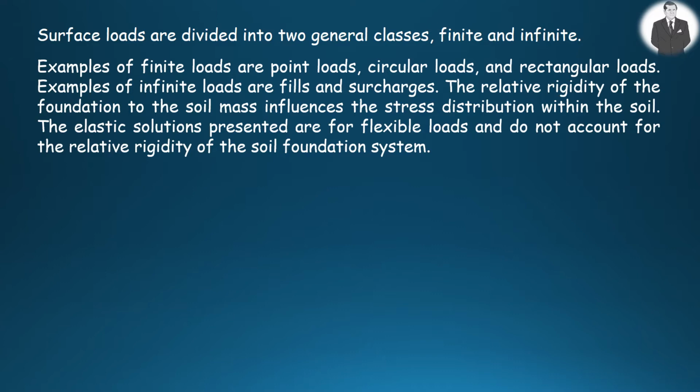The relative rigidity of the foundation to soil mass affects the stress distribution within it. Therefore, the elastic solutions presented here are for flexible loads and do not take into account the relative rigidity of the soil foundation system.